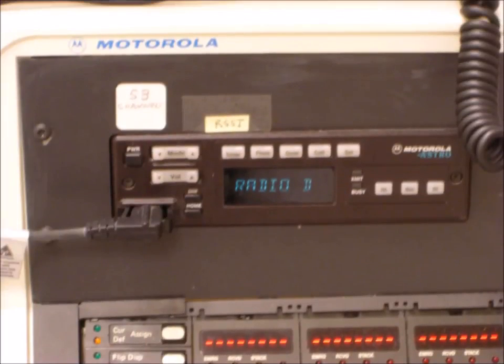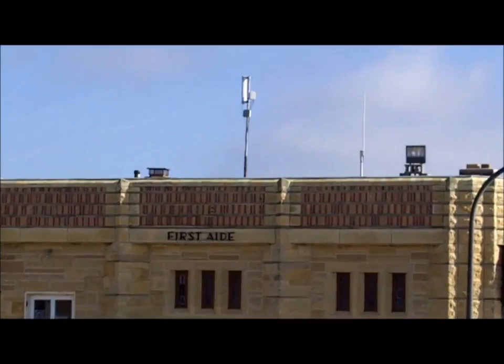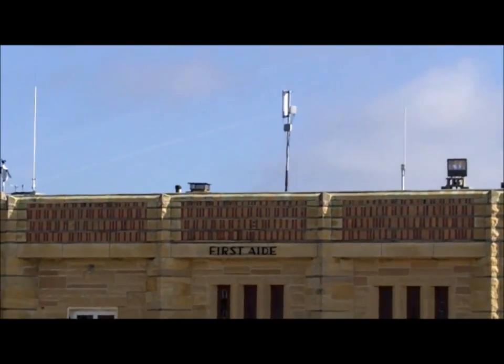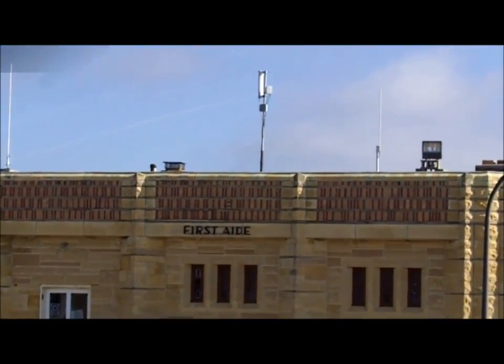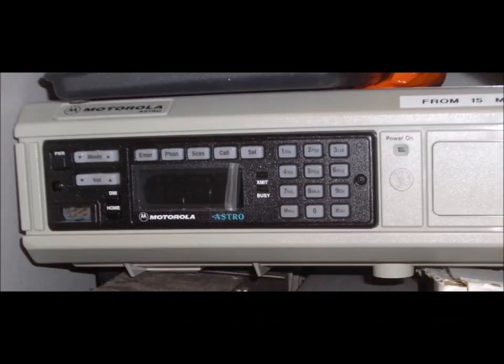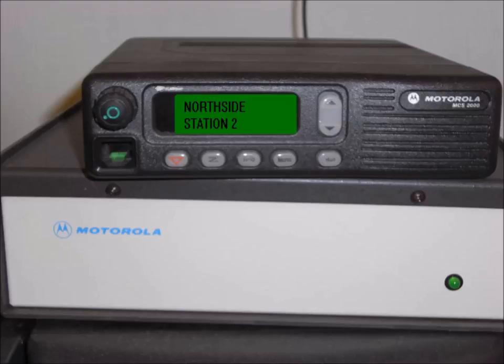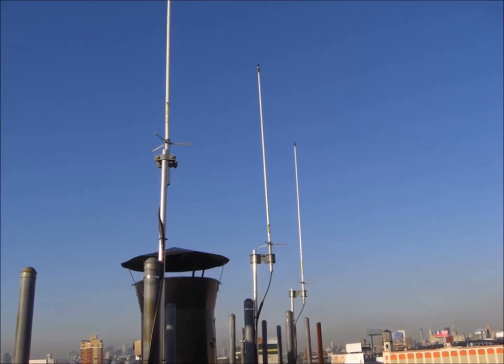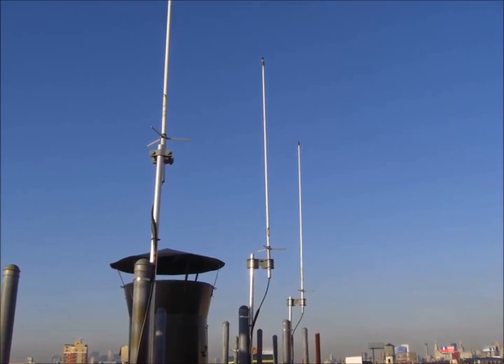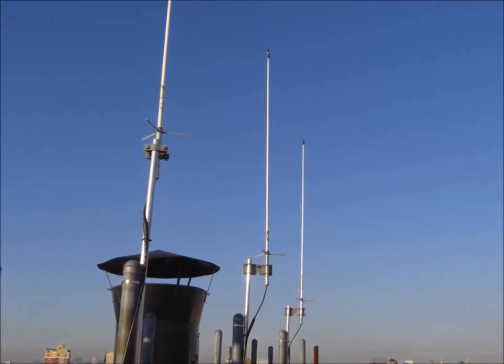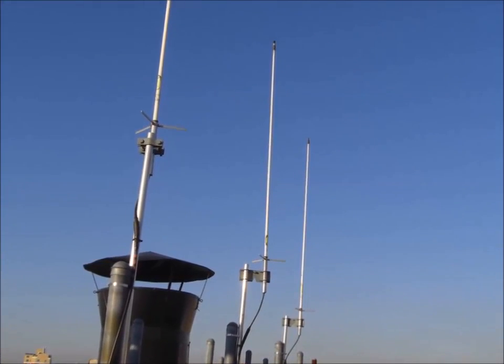Sometimes a desktop radio is needed. A simple desktop radio can be made from a mobile radio mounted with a power supply and connected to an external antenna. These may be used in fixed locations like a police station or firehouse, where a user may need to contact units in the system without dispatcher intervention, or perhaps as a means of system monitoring. Depending on your system configuration, a desktop radio could be used as a backup to the dispatch system in case of a console failure, or as an alternate dispatch location for redundancy.